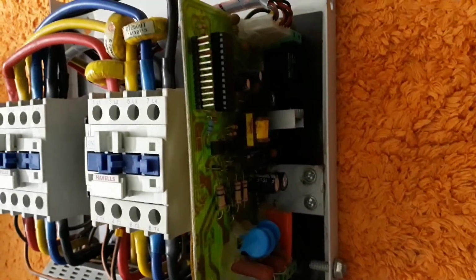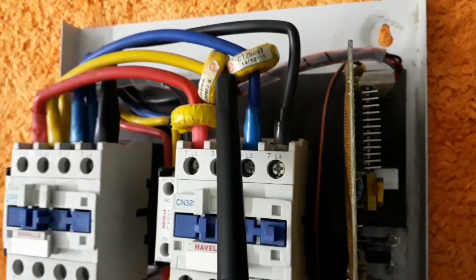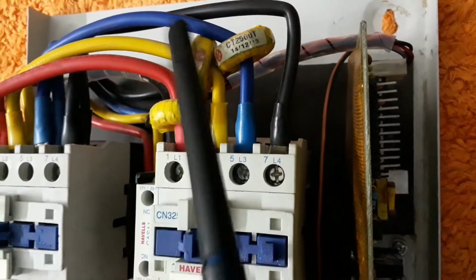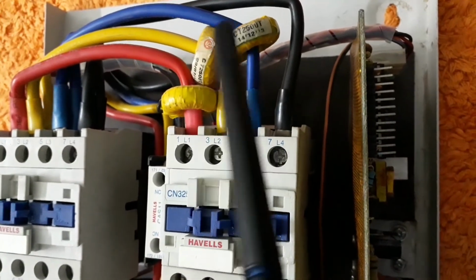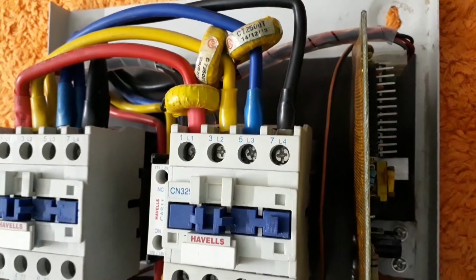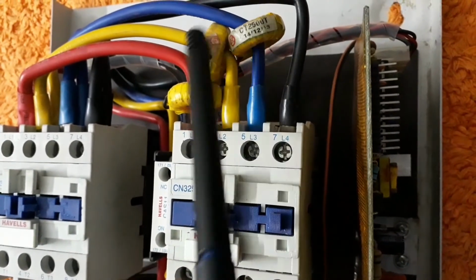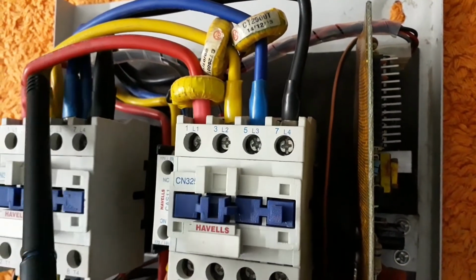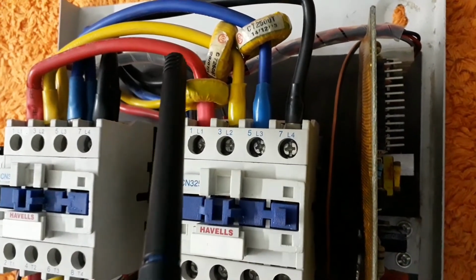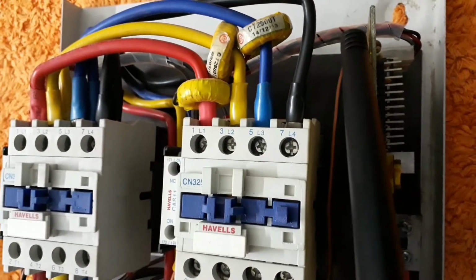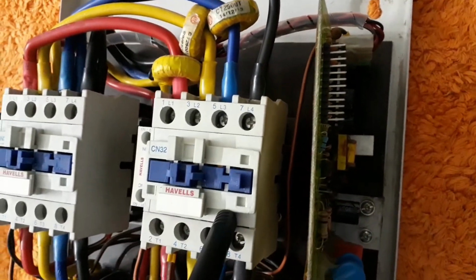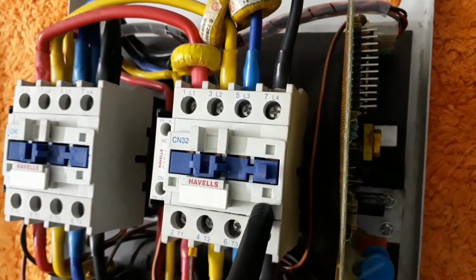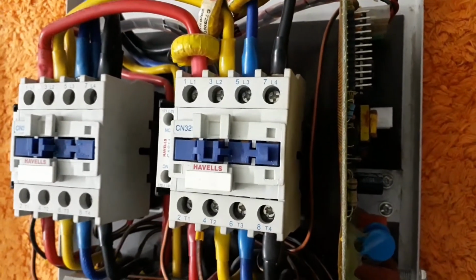the current consumption by our house. Here we have 3 current transformers connected to each phase, blue, yellow and red. These are current sensing transformers that sense how much current is going through these wires, and if it exceeds 8 amperes, then this logic circuit card will disconnect the relay, and your house will get disconnected from the DG load.